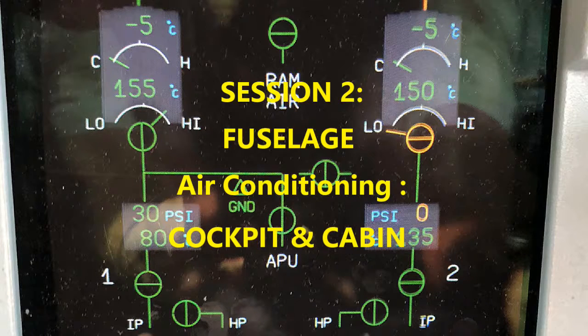So with the mixer, you also have a mixer flap actuator. That actuator is operating a flap in the cockpit supply port of the mixer. Just so you have that knowledge that it is there. What happens is the flap is going to change position based on the actuator movement, and that's going to happen with depressing or putting the pack switch to off.